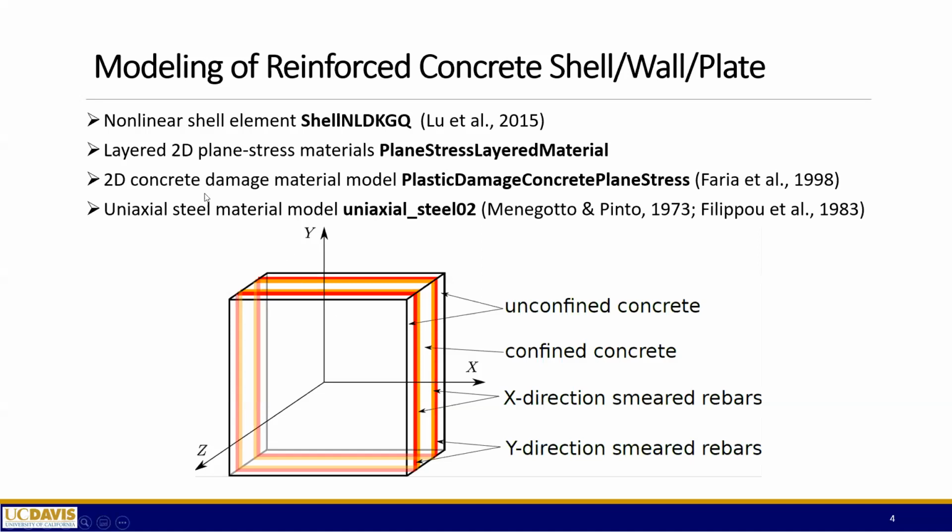So for the concrete material, we have the 2D version of the concrete damage material model. Here is the DSL keyword for that. This model was originally developed by Professor Faria and his colleagues in 1998. When it was developed, it was actually a 3D concrete damage model, but here we are using the plane stress version, the 2D version of the material model.